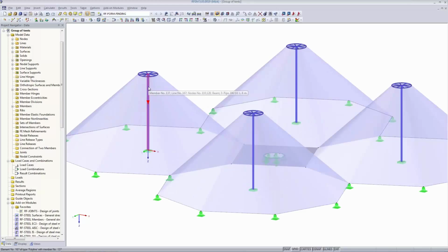This is something we did already in the first example as well, where we looked at the cone, but I didn't emphasize this as much. It's important that you don't create any singularities up here. If you would build up the cone up to the far top, then you would definitely end up with a singularity, and this is not something we are interested in. It gives failed results. So that's something I come back to later on, these fixed supports. For now I keep them as they are,